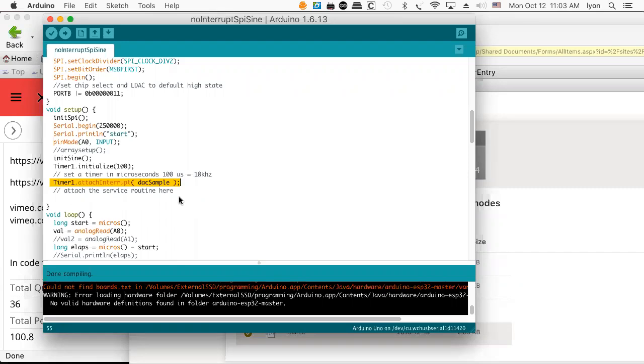I've looked at the code. It's quite extensive. It doesn't seem to compile at all in the Tinkercad, which is really unfortunate because I tried like crazy to get that timer 1 ported over to Tinkercad, but I just couldn't do it. Tinkercad apparently is not as faithful a simulator as we might like. So there are limits to simulators. In any case, sampling every 100 microseconds means sampling at 10 kilohertz.